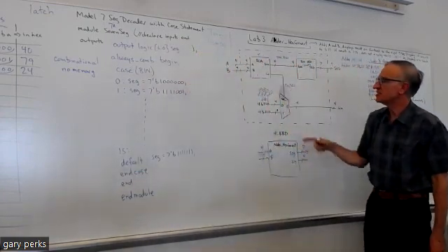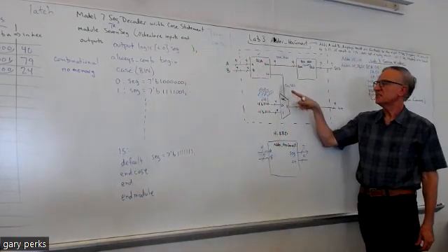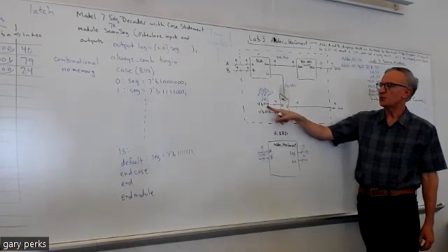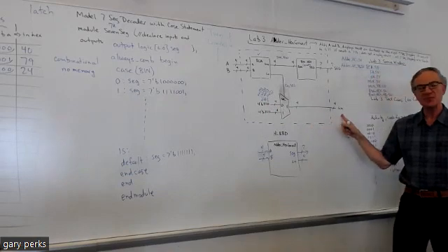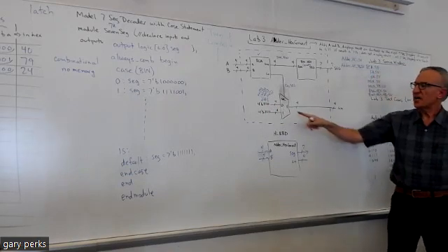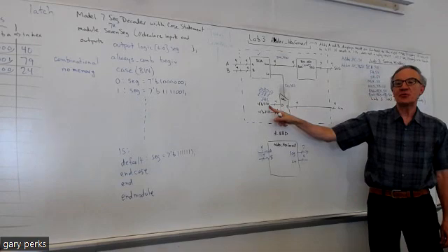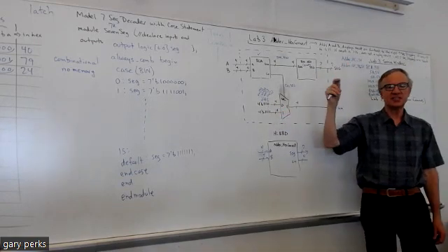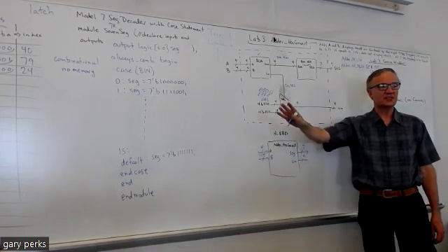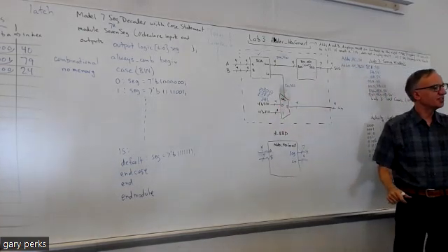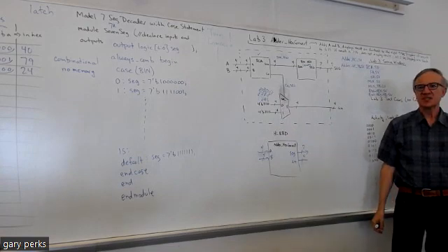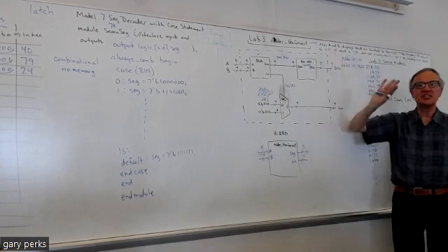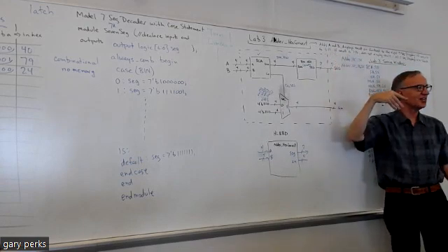Okay, and then if our result is 15 or less, we'll have a select of 0, and that's going to put this data 1, 1, 1, 0 at the output of the mux, which is going to be our AN. So that will turn off all the displays except for the furthest to the right. Therefore, since the result of our addition is 15 or less, it will show on our display. Okay, so you see how the mux is making this happen as far as when the result is shown and when it's not shown.